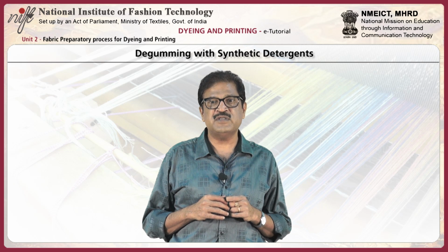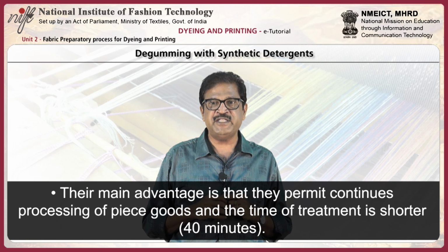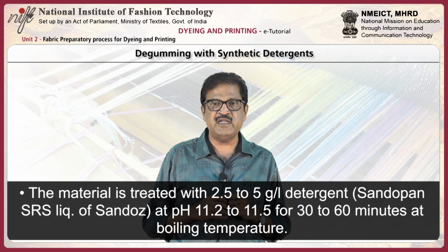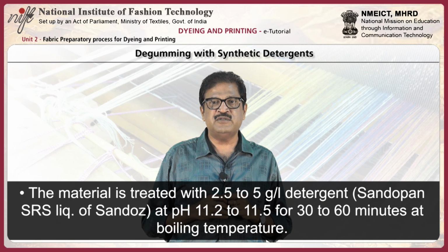Silk degumming process with synthetic detergents. Synthetic detergents are now being increasingly used in place of soap. Their main advantage is that they permit continuous processing of piece goods and the time of treatment is shorter, about 40 minutes. In this method, the material is treated with 2.5 to 5 grams per liter detergent at pH 11.2 to 11.5 for 30 to 60 minutes at boiling temperature.